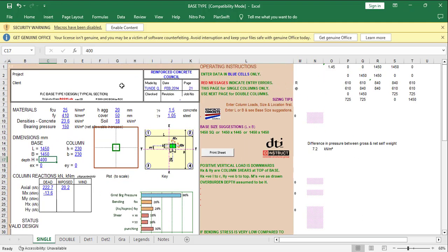So what is actually contributing to this is also this bearing capacity. For example, if I increase this bearing capacity to 200, you will discover that even when I drop, you can see by just increasing the bearing capacity, that means I am assuming that this soil is better than what the initial information I specified.